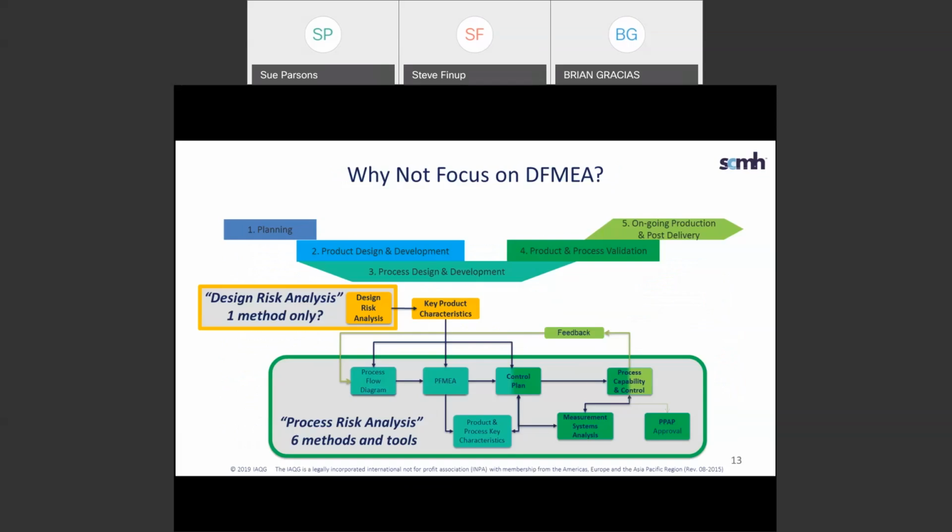Now, I'm going to try to answer a question which has come up since we first aired this webinar back in November of last year, and it has to do with why we do not just specify design FMEA in the 9145 standard. So what I wanted to do here is just have us consider the entire APQP suite of methods and tools. If you look downstream of design risk analysis and KPCs, or key product characteristics, you'll see a whole set of tools and elements that we are going to talk about in follow-up webinars.